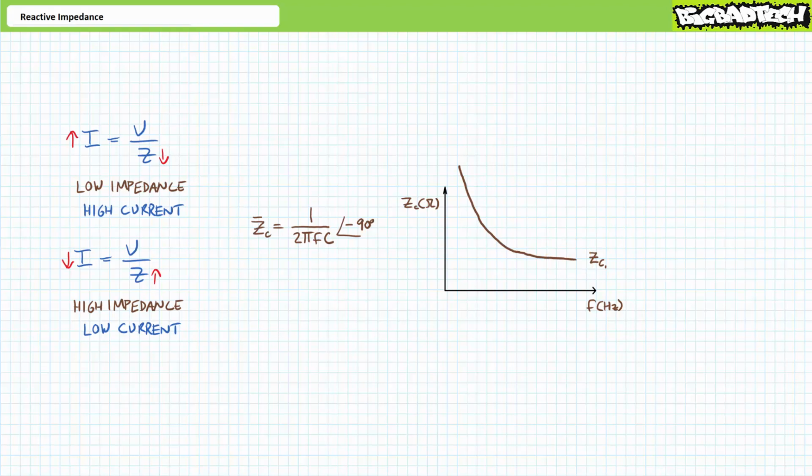Frequency is the rate of polarity oscillation. Lower frequencies correspond to slowly changing waveforms, where 0 Hz, or no change, represents DC. Capacitors at low frequencies present large impedance. Think about it. What's the steady state impedance level of a capacitor in a DC system?